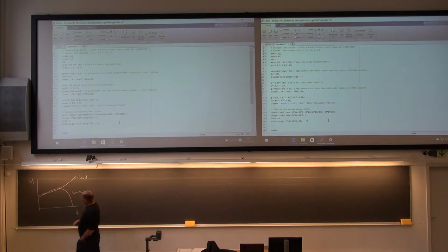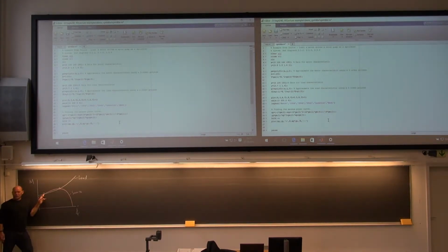Look at the first one, for instance. If you reach this point exactly, you are in balance between the source and the load, everything should be okay. So you should be able to run at this speed, given this torque, for as many days as you like. But see what happens. If you go a little bit to the left, here, then your source is too weak.